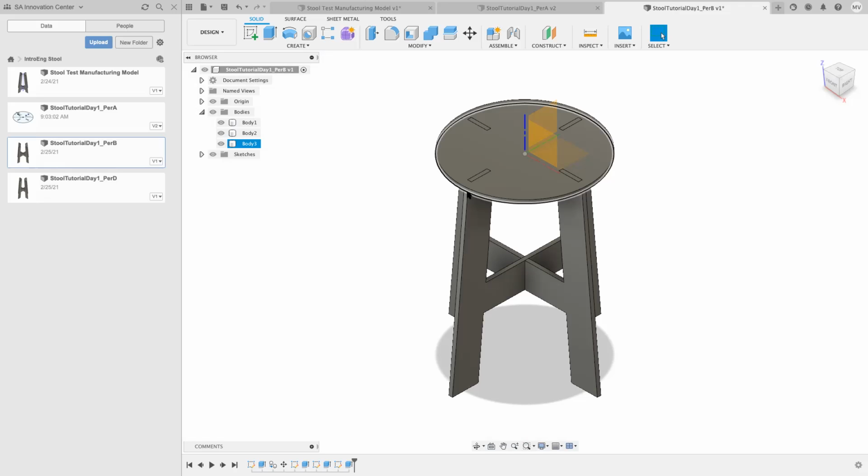This is a ball nose end mill. So we call these end mills, or we can also use router bits. But they're drill bits that are strong enough and sharp enough that instead of just being able to go up and down, make holes, you can go down and then you can move it sideways to cut like a saw would cut. But it's going to be this thickness.